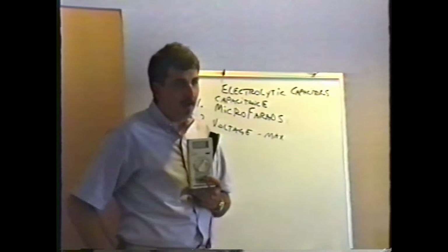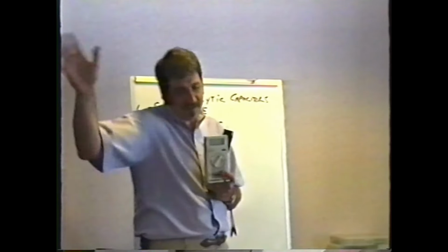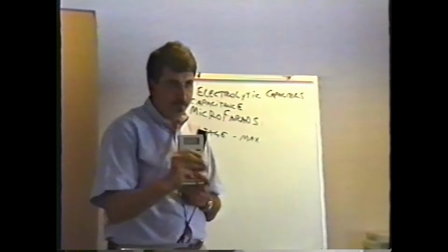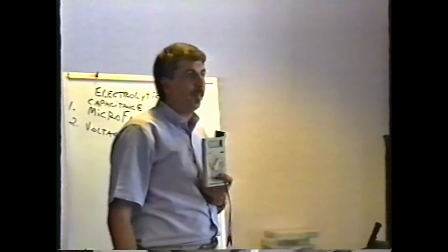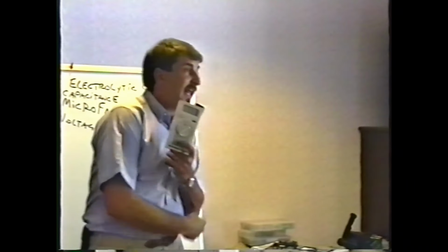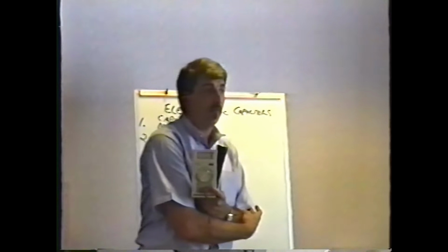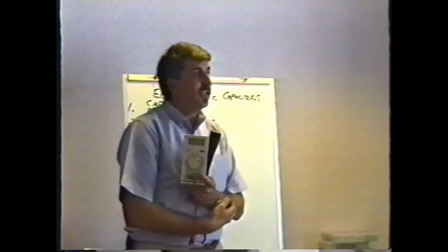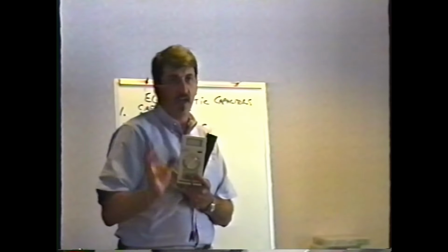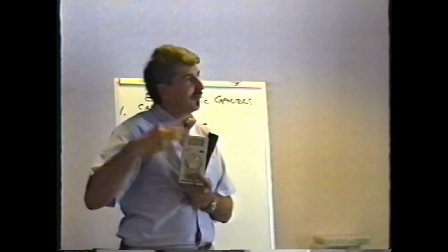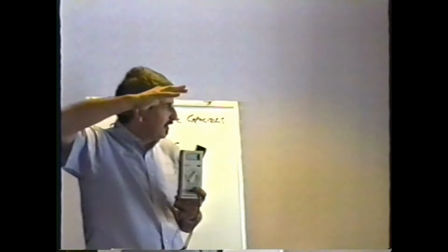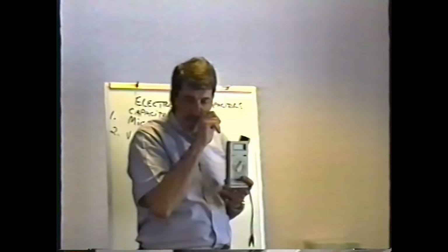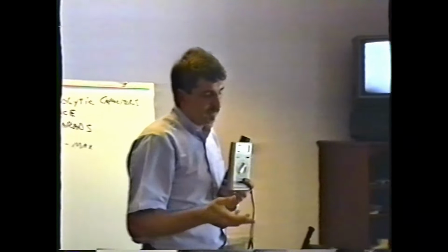Sure enough, it doesn't come on. I'm going, well, let me just fix it. No, you wait, you see. Okay. Yeah, 5 minutes later, boing, the thing fires right up. Bad capacitor. Capacitors are funny like that. Sometimes when they're cold, they won't work, but as they warm up, the problems go away. You see this on monitors a lot. When you first plug it in, it looks like crap. And then after it heats up, the sides straighten out a little bit, and it gets bright, and it looks okay. Those are typical capacitor failures.